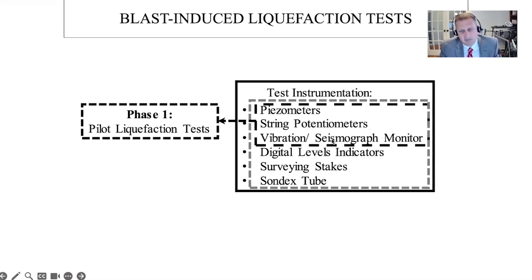Because this is near a flyover, when we first started blasting, I was a little bit concerned that we might cause some issues associated with surrounding infrastructure, but we didn't see anything. The way that the blast charges are set up, it directs all of the energy into the location where the pile's in the middle of the blasting ring, and so we're forcing all the energy into the pile, not away from the pile.